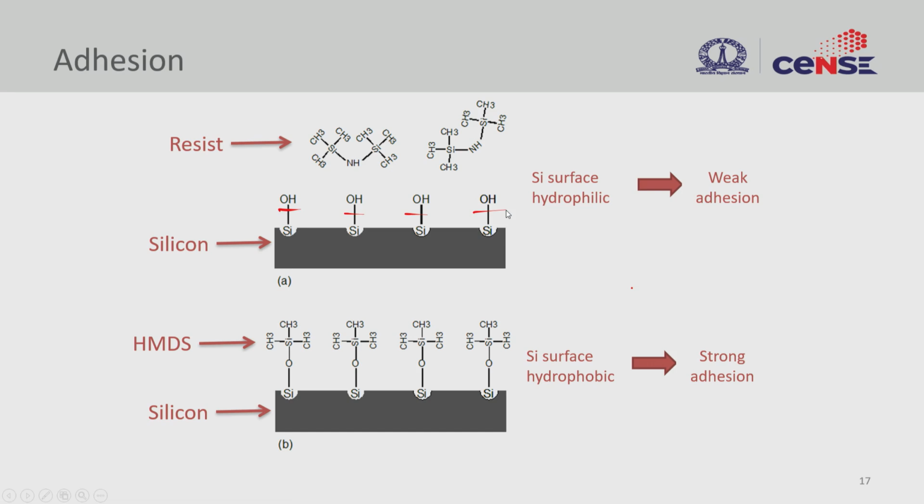When you come in with a resist, you might have a hydrophobic surface, and you want to make sure whether the substrate is hydrophobic or hydrophilic in order to get the right adhesion. To achieve good adhesion, adhesion promoters are required. This is something that we also saw in the lithography process steps. Adhesion promoters are essential to stick your resist onto the substrate, and also to make sure that after patterning these structures stay on the wafer.